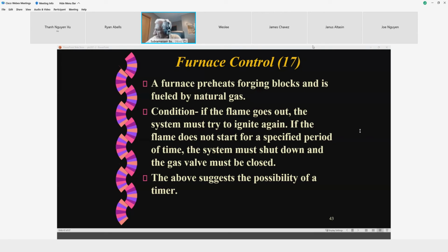Well, this is the operation of a real furnace at home. I'm talking about a high efficiency one. You set the thermostat to 20, 21, whatever, Celsius. Okay? These are all digital thermostats operating on 24 volts or 12 volts or whatever. It's not 110. On a high efficiency furnace, this is what happens. When the temperature goes below what you set, 20, it will kick in even at 19.9. Very short bandwidth. Okay? It'll come on.